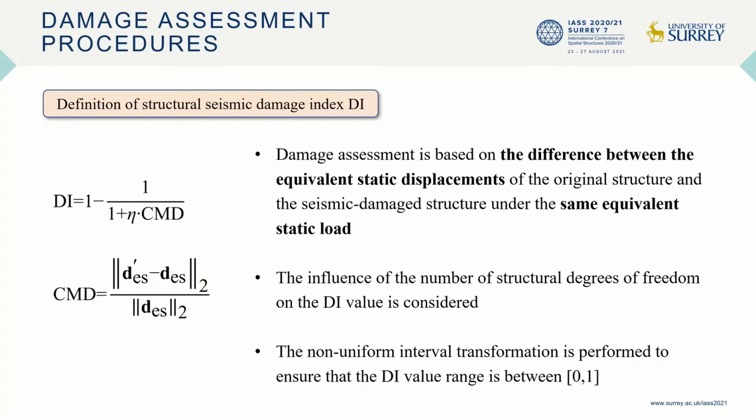On this foundation, the structural deformation capacity or seismic damage degree can be assessed based on the difference between the equivalent static displacement of the original structure and the seismic damaged structure under the same equivalent static load. We use these two formulas to calculate the seismic damage of the structure.